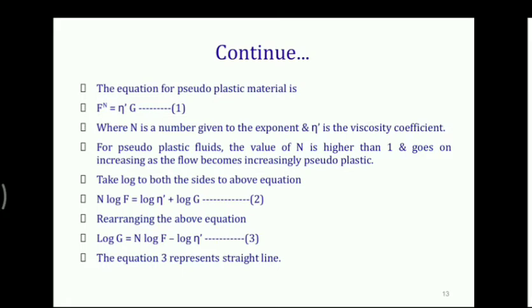That is why we are converting it into logarithmic form. Why is the logarithmic equation required? Because the entire pseudoplastic curve is non-linear, so we are not getting useful information or data. When the equation is converted into logarithmic form, it gives a straight line, and from the straight line we get the useful data. So this equation 3 is applicable for the pseudoplastic system or shear thinning system.